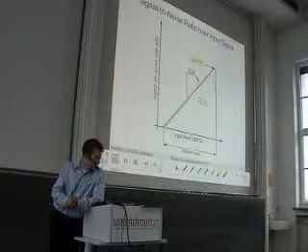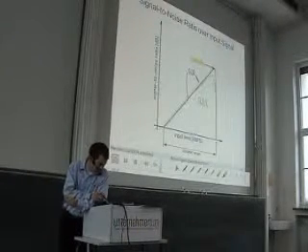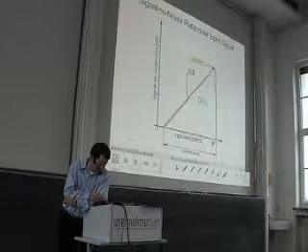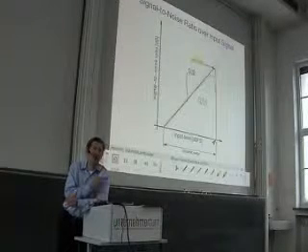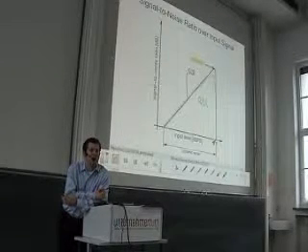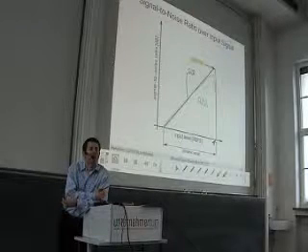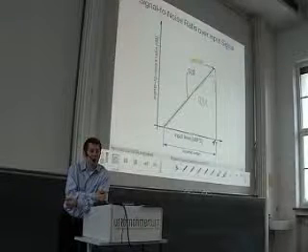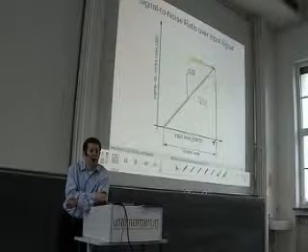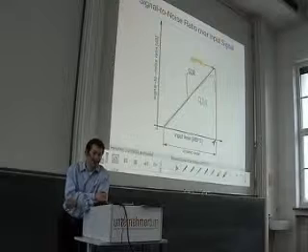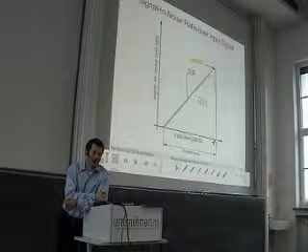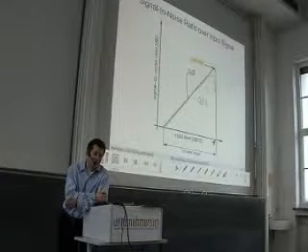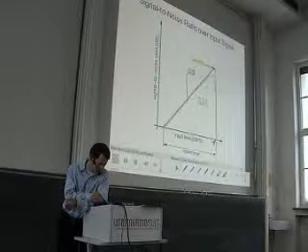You're right. So the question was, how can we define the dynamic range like this? Also, we cannot use the device in this region. Well, it is defined like this. So the peak SNR is the more reasonable value to understand what the ADC can really perform. Yes, absolutely. But you have to make really sure.